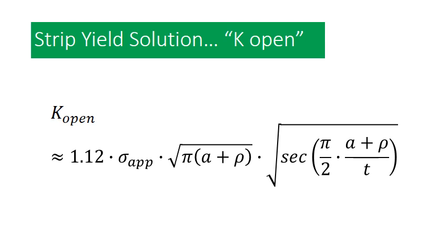It takes into account that as your crack gets closer and closer to the back wall of the pipe, whether you be coming from the internal or external, there's actually going to be a magnification of the stress intensity factor. So what I've done here is I've included that term, and that all comes down to the crack depth including the plastic zone, remember, because we're looking at the stress intensity at the tip of the plastic zone, and divided by the wall thickness of the pipe. So hopefully that makes a little bit of sense.